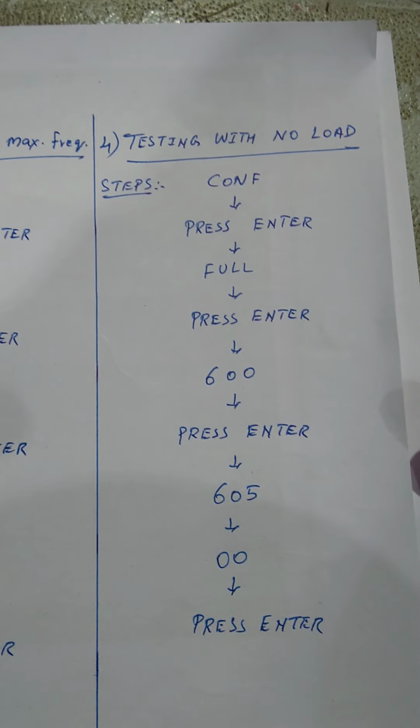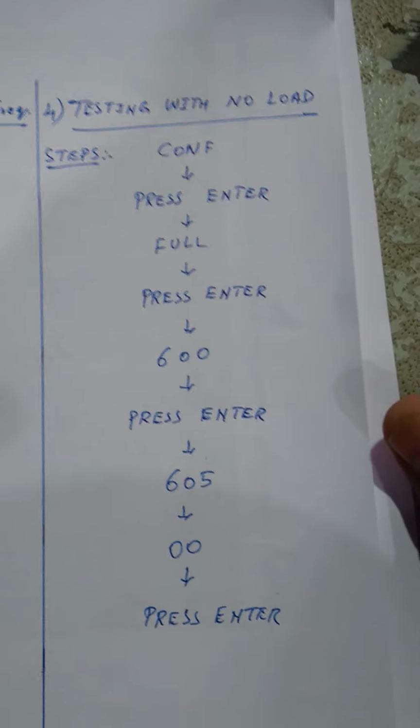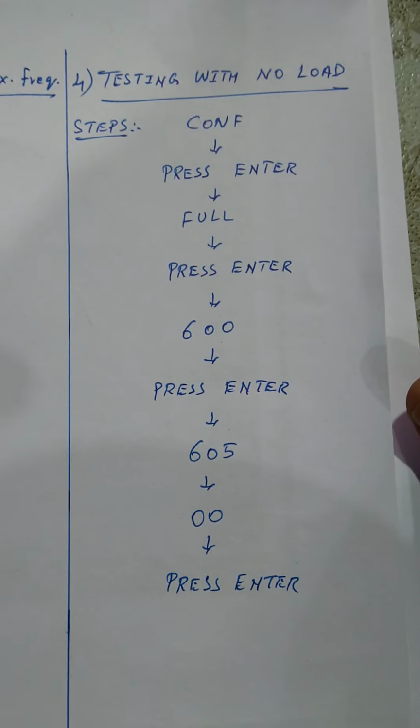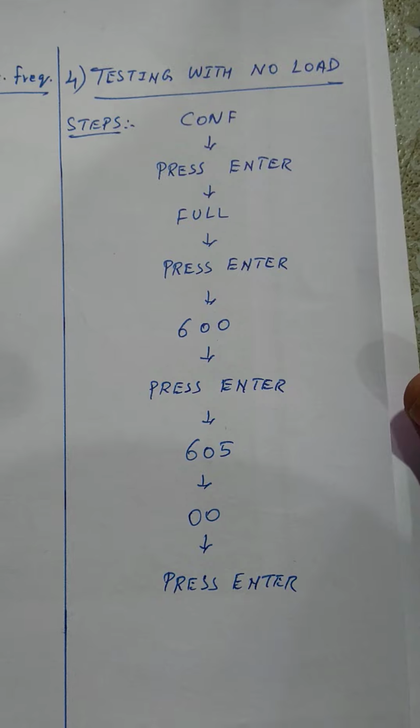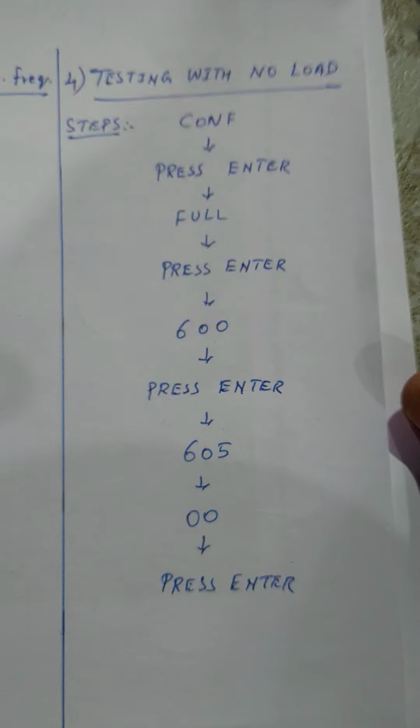So if you want to check the VFD with no load or no motor, then we have to configure this parameter, testing with no load.